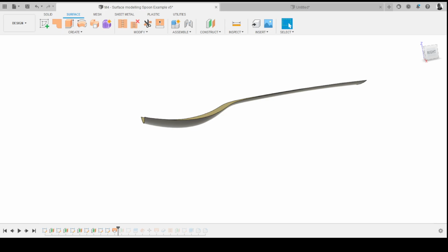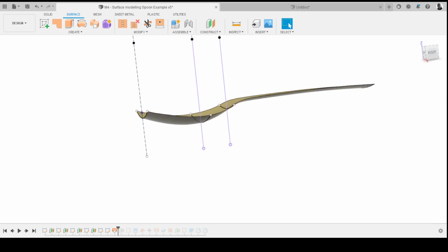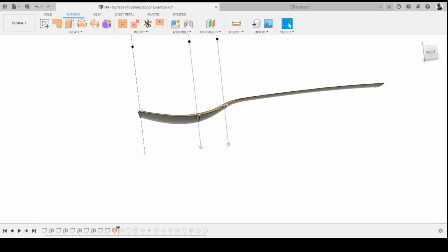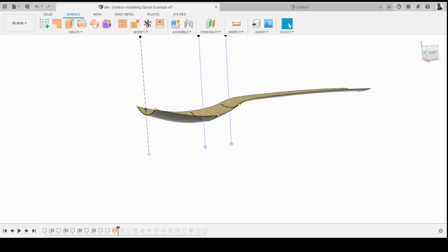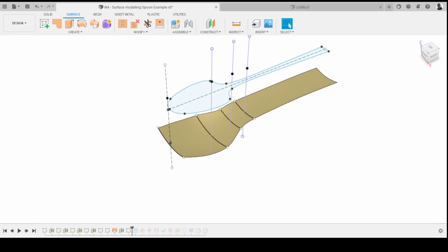But yeah, if you wanted to do that, you'd have to match some of those profiles, perhaps down here, so even ones underneath it, and then start moving away to a thicker loft. And then you'd have 2 surfaces, one on top of the other, which you would then cut through with your cutout. And then you could loft around the edge and stitch it together.